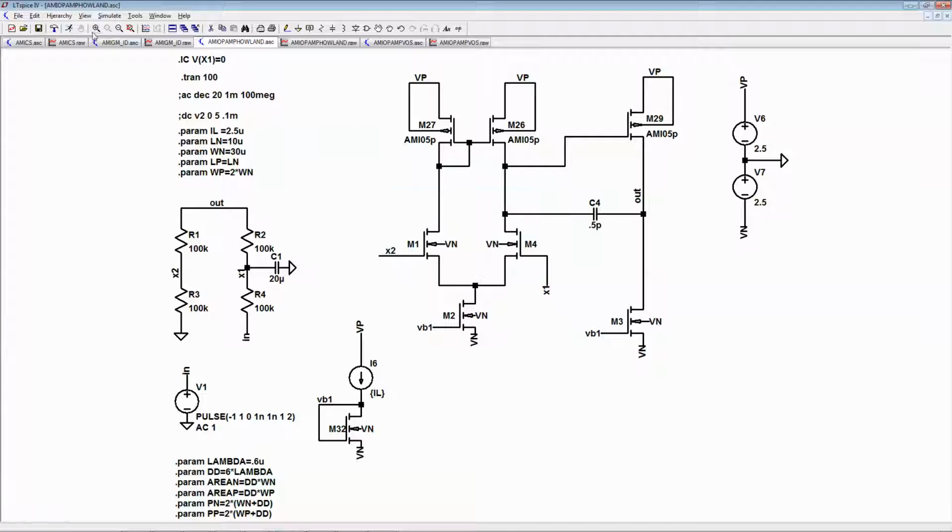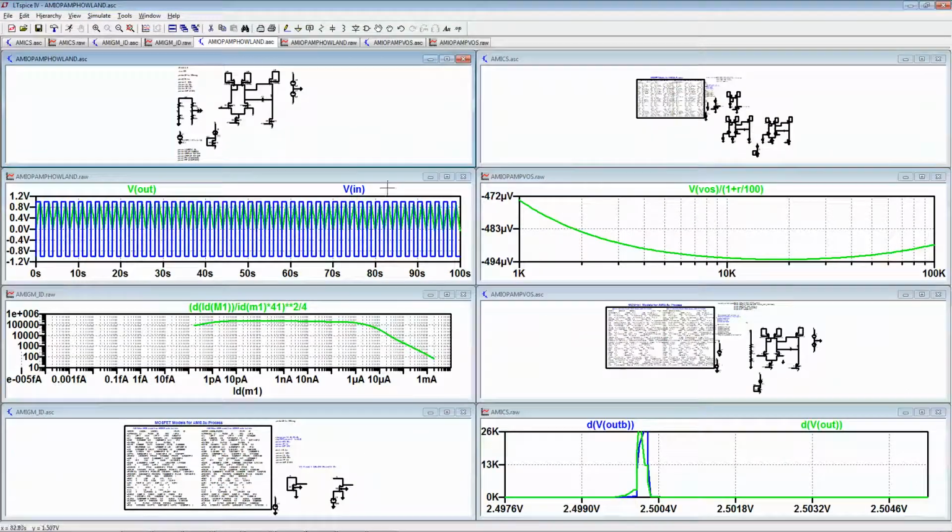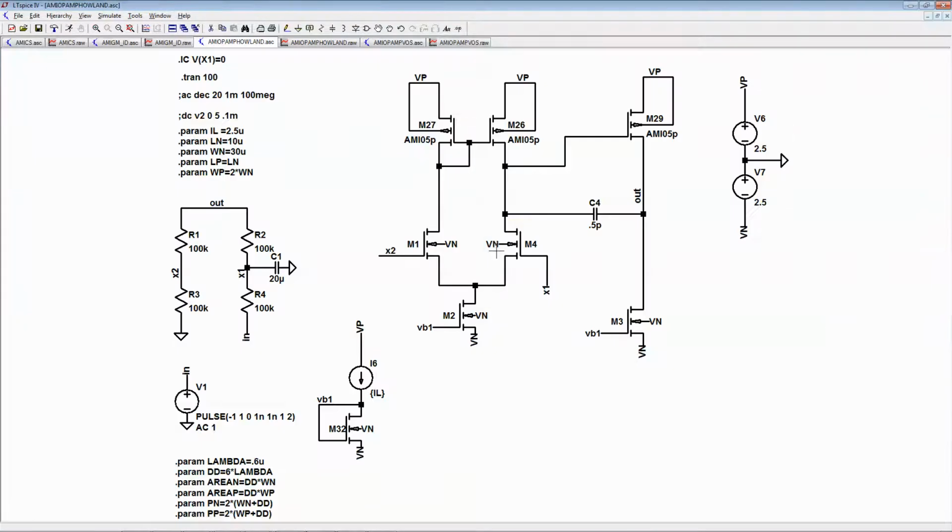So a little more confident about what we're doing. Still, now we can, if the offset voltage is too large initially, it can be problematic. And so we might have to, for at least if we use the Howland, put something here so that we can offset that DC so that these integrators work right. But this seems pretty good. Now, yeah, we have to kind of,